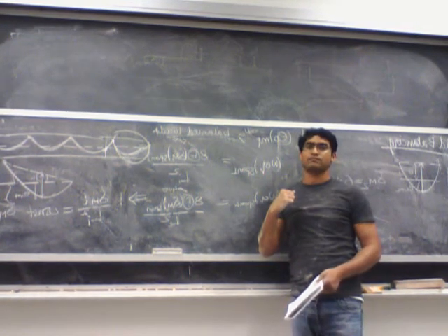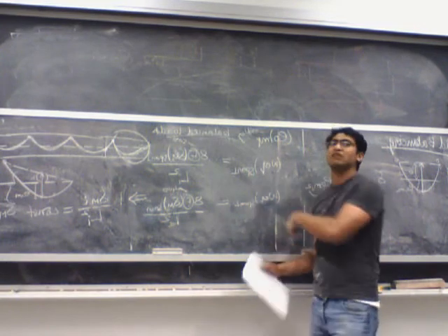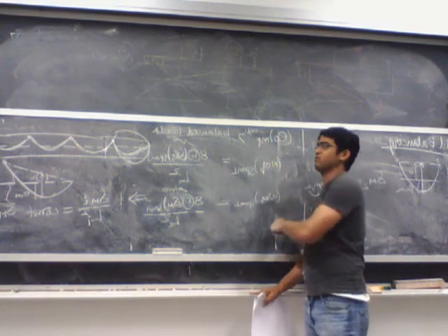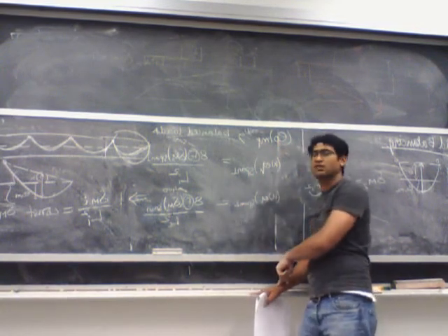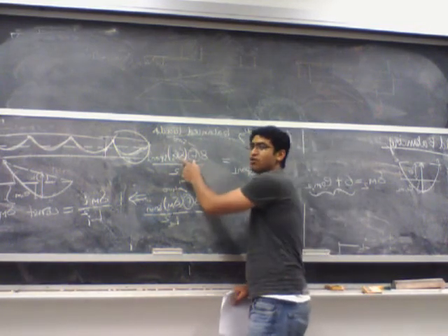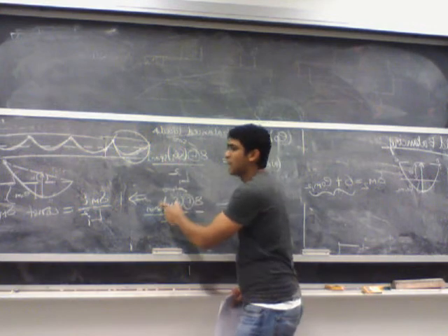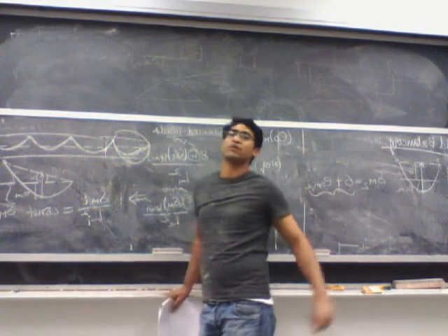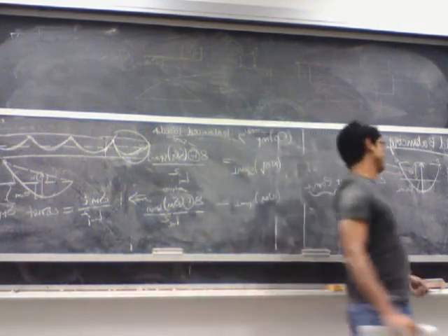Once you have the final value of F from comparing all the spans, you can go back, put in the final value of F and calculate the actual delta M for each one of the spans. So it's kind of a repetitive process.